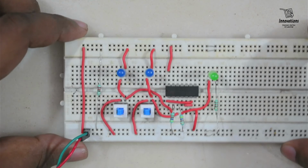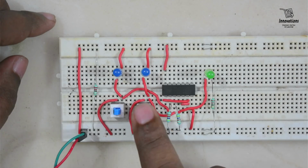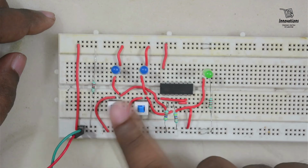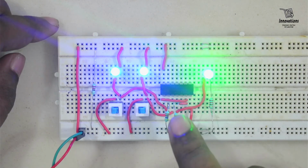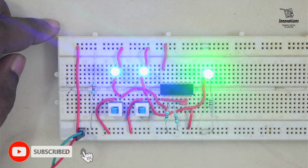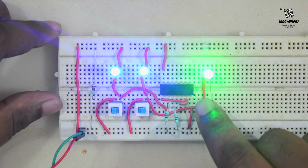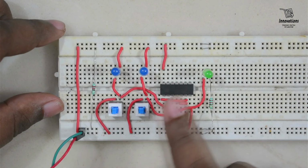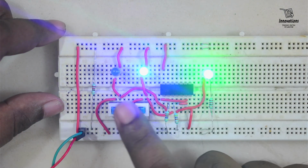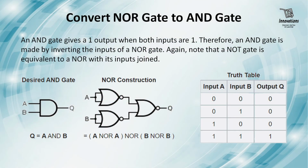Now we will match it with the truth table of an OR gate. So 0, 0 gives output 0; 0, 1 gives output 1; 1, 0 gives output 1; 1, 1 gives output 1. So this circuit satisfies the truth table of a 2-input OR gate, and thus we have successfully built a 2-input OR gate using two NOR gates. If both the inputs are low, then the output is low, and if any of the inputs are high, then the output is high.